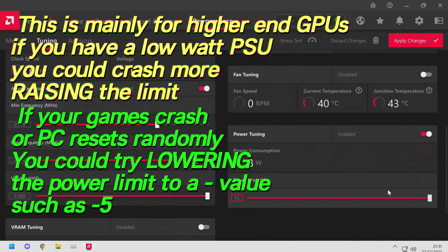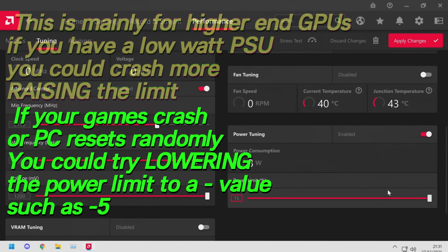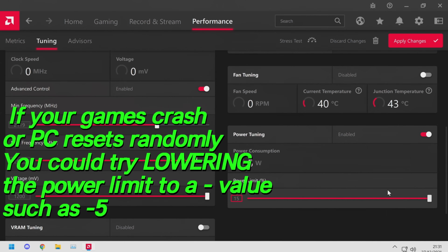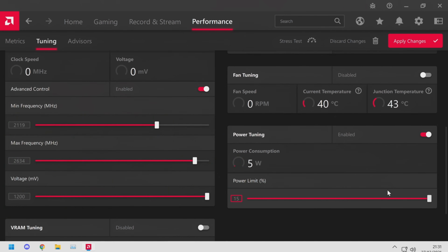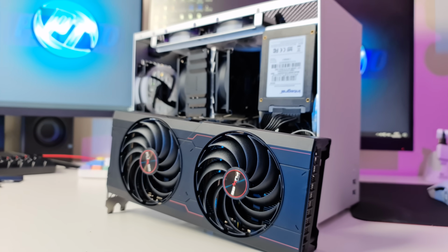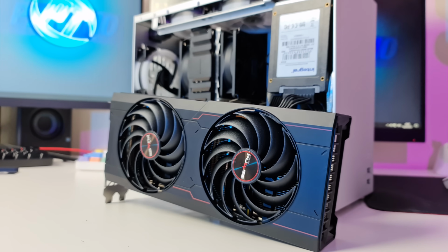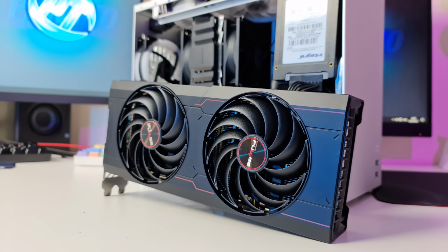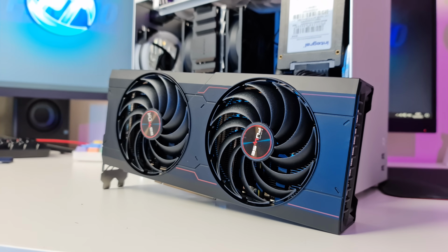For any of you that are on maximum GPU loads, you can actually have your GPU accept a little bit more power, getting you some more performance, helping stabilize those maximum frequency clocks. We won't be causing damage to the GPU from doing this. All GPUs are BIOS locked, so you cannot set values which can damage your GPU in either the AMD Radeon settings panel or the Nvidia Control Panel.